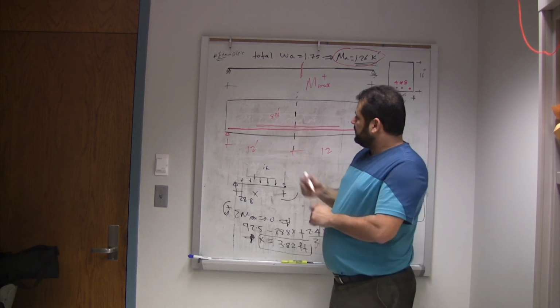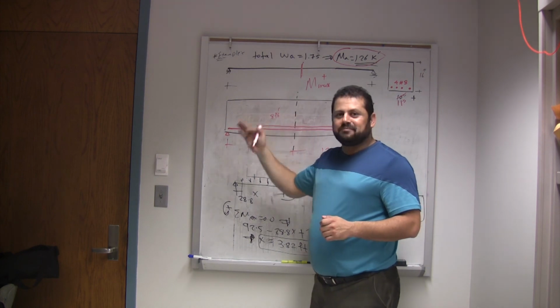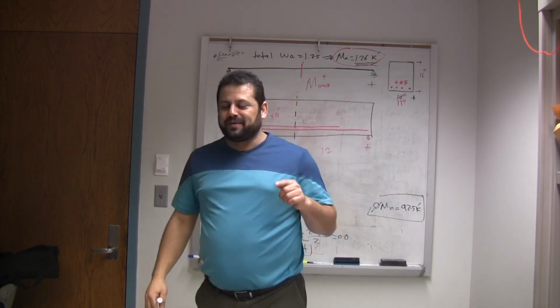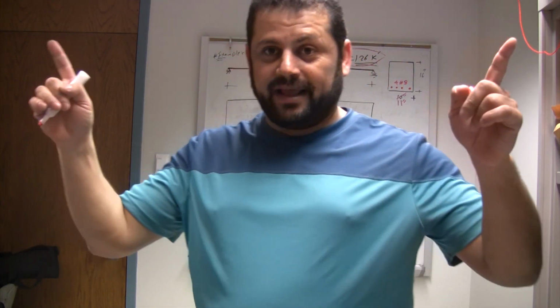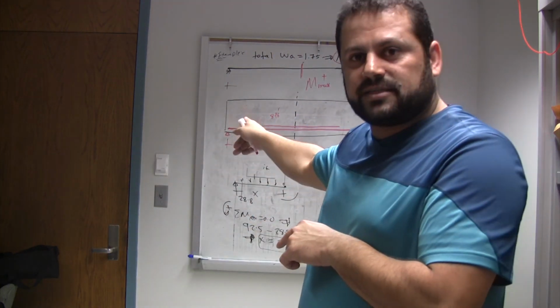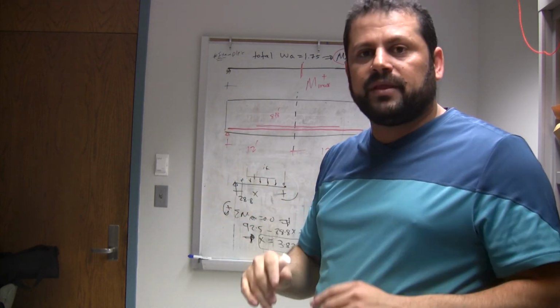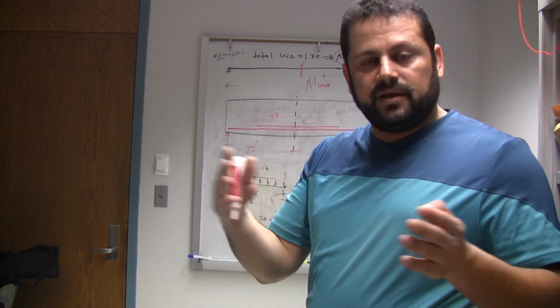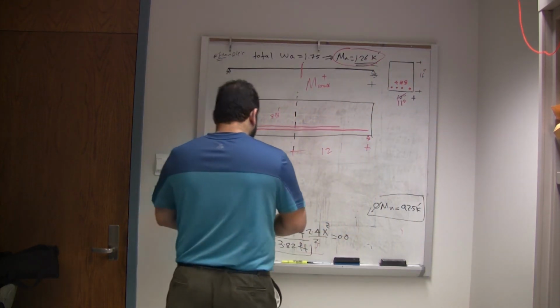Now look, from that distance to this location here, this length must be greater than the development length. I'm going to explain later why. That length must provide enough development length for the bars to develop their Fy in the middle. In the next lecture, I'm going to explain everything about the development length, and you're going to understand why. But now you know how to calculate the cutoff points, when we can terminate some bars, stop 2 of them, stop 1 of them, and all of that. And see you then. Thank you, Gerard.